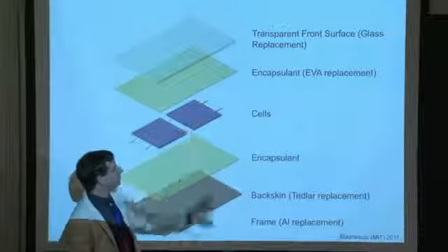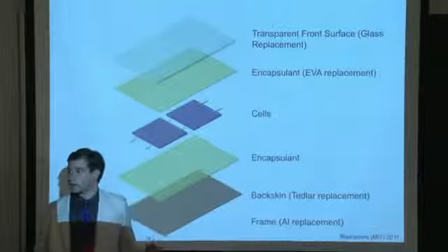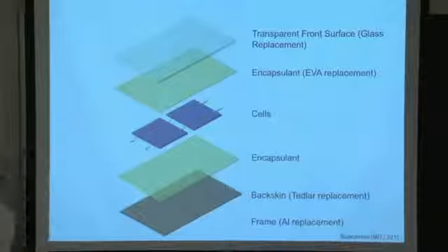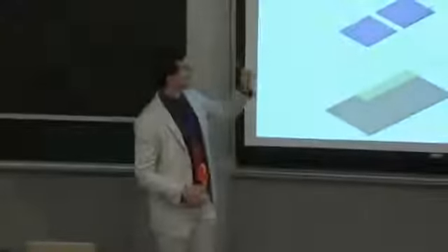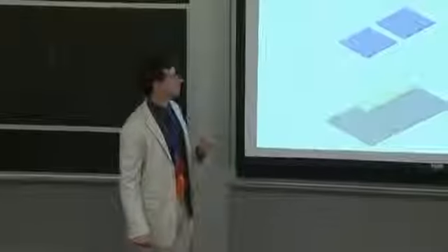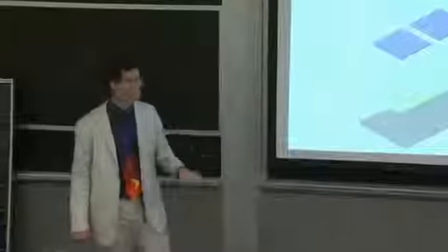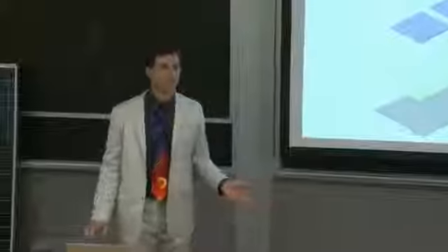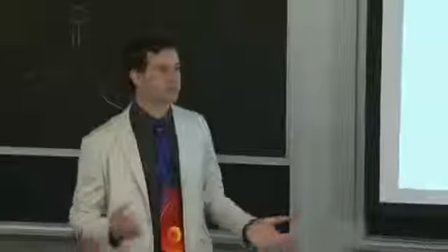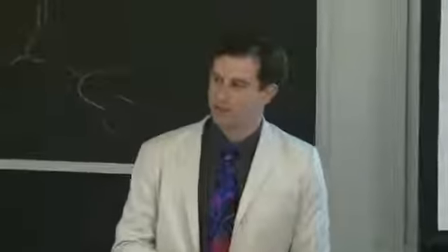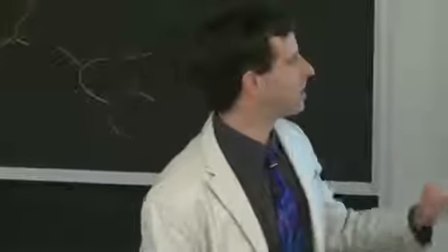In terms of moving to new materials, there's a lot of work right now to squeeze the commodity costs out of solar module manufacturing. If you look at the percentage of cost of commodity materials in the solar module, it is quite high. And so people are focusing on new types of transparent front surface materials that let the light in, glass replacements, right? You could envision, we have many examples of really hard, resistant polymeric materials in our daily lives. People are looking into those.